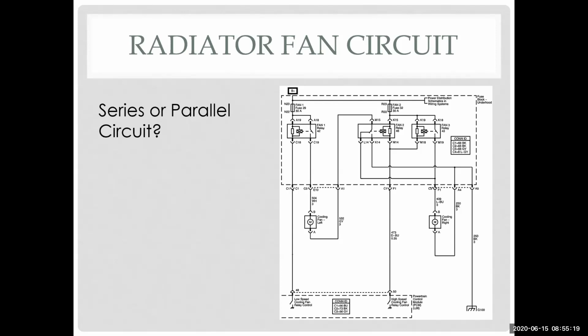Does it have anything to do with when the fan turns on, but way too late? This would not, because that's controlled by the temperature sensor. So these are the fans for the radiator. Right. Well, on this system, the temperature sensor goes to the computer, and the temperature sensor is actually on the engine, mounted right by the thermostat on the engine side of the thermostat.